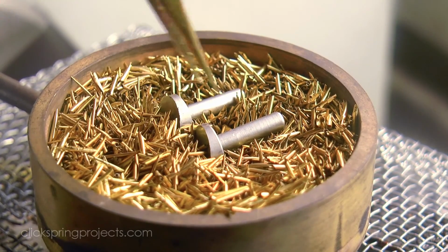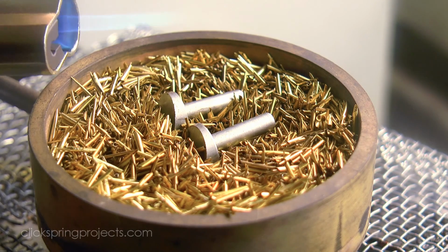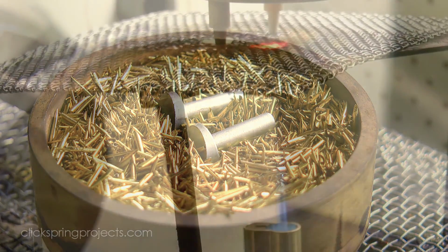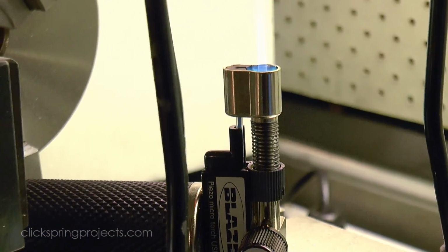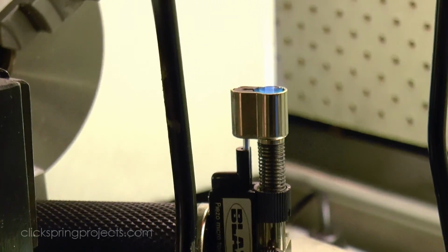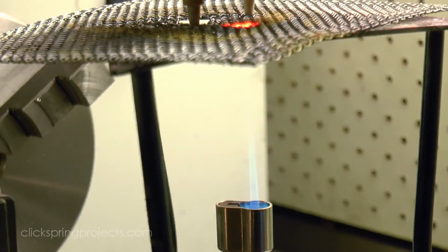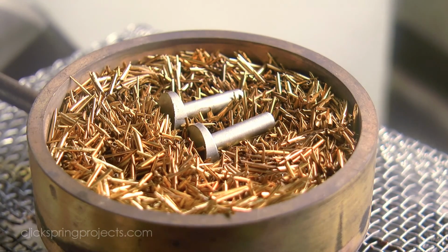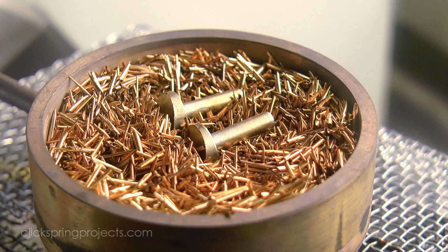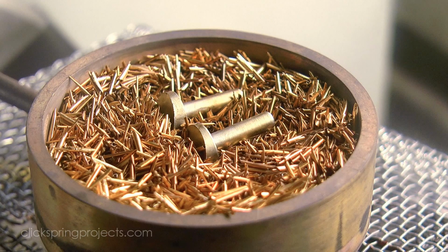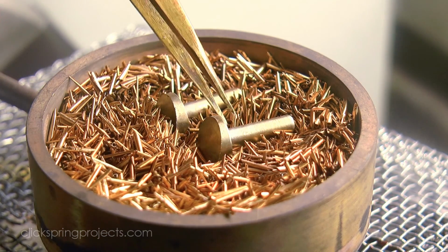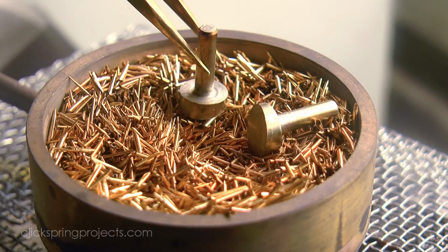This is the same setup you've seen for bluing screws, except this time I'm stopping well short of blue. In fact, I'm barely letting any colour develop at all, aiming for the shade generally referred to as pale straw. It corresponds to a temperature of around 230 degrees Celsius, and it'll give a hard cutting edge with a small amount of toughness. And you can see it's not that much of a colour change at all, just the barest change to yellow. A small trade-off has been made within the structure of the metal, with the glass-hard martensitic structure being slightly transformed into something a little tougher.